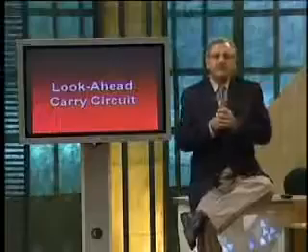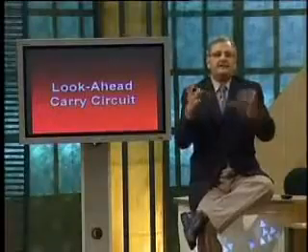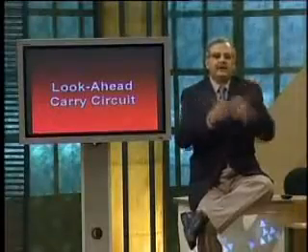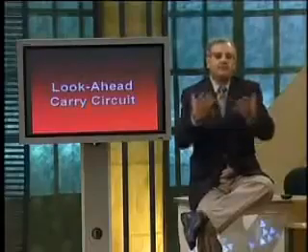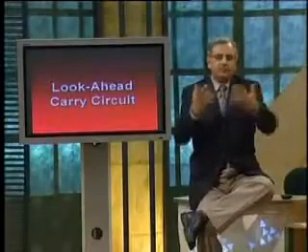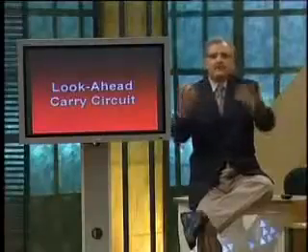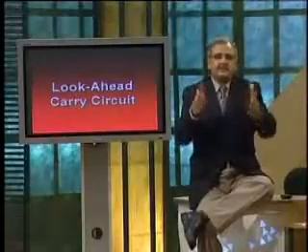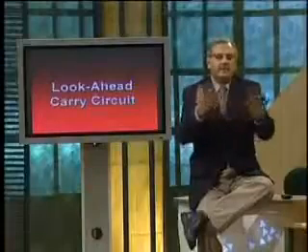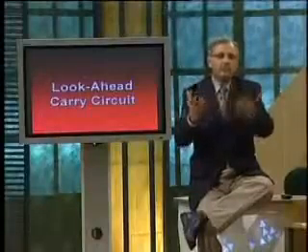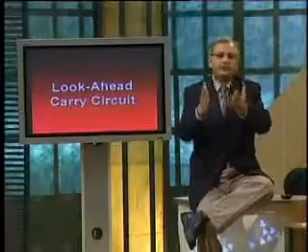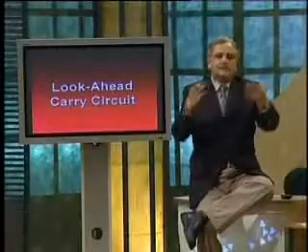Now in today's lecture, we basically looked at the adder functional unit. We started with the half adder, then we looked at the full adder. We made the function diagrams of both adders, derived the expressions and implemented them. Then we said that a single bit full adder cannot do any useful work. So what do we do? We need to combine such full adders to form a parallel adder.